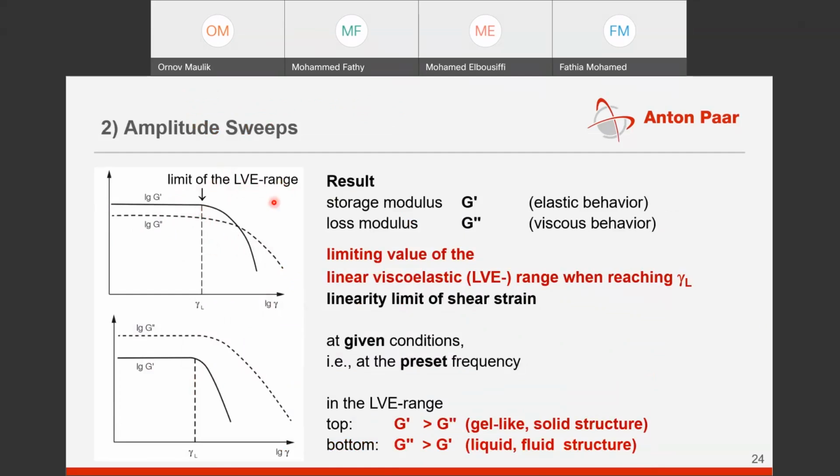So you will get the linear viscoelastic range, and it is really very crucial in order to get information about the physical stability. If you are working with polymer melts, it is really very important to characterize this linear viscoelastic range, because this particular range of deformation is to be used if you are doing any temperature dependent tests or time dependent tests or anything else.